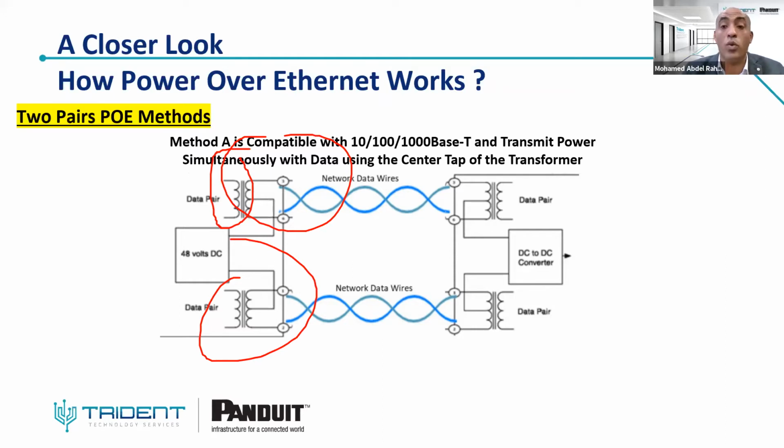One important thing to understand when you are talking about PoE is that the power is transmitted over the data by applying something called common mode. Common mode means that the power, or the current, will be split between two conductors equally. So if you transmit current inside the pair, you have two conductors for each pair, and the current will be transmitted equally in each conductor. So you need to achieve the requirement that the two conductors have the same, or equal, resistance.